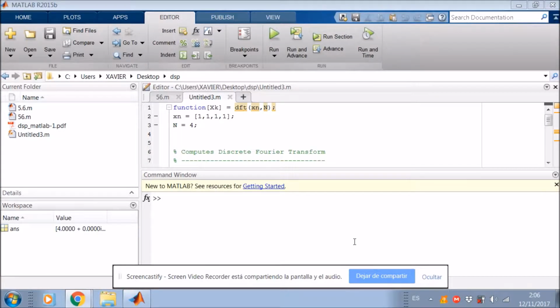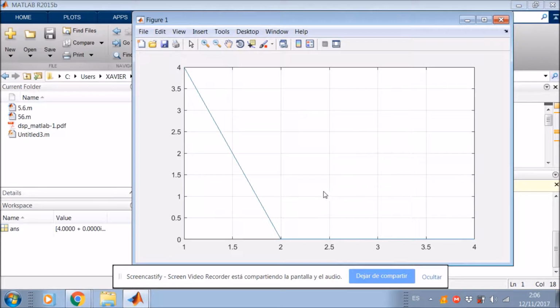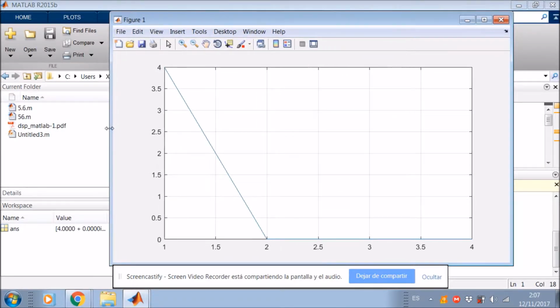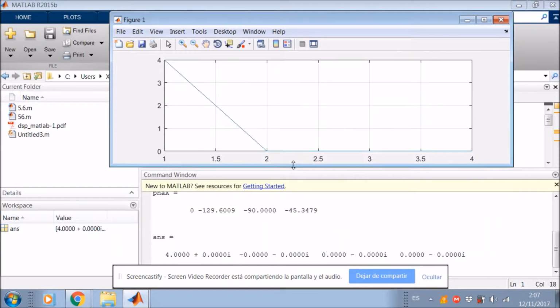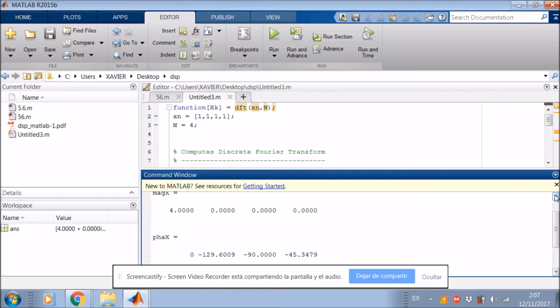When the magnitude sample is zero, the corresponding angle is not zero. It is due to a particular algorithm used by Matlab to compute the angle part. Generally, these angles should be ignored. A plot of the DFT values is shown in the figure. The plot is also shown as a dashed line for comparison.